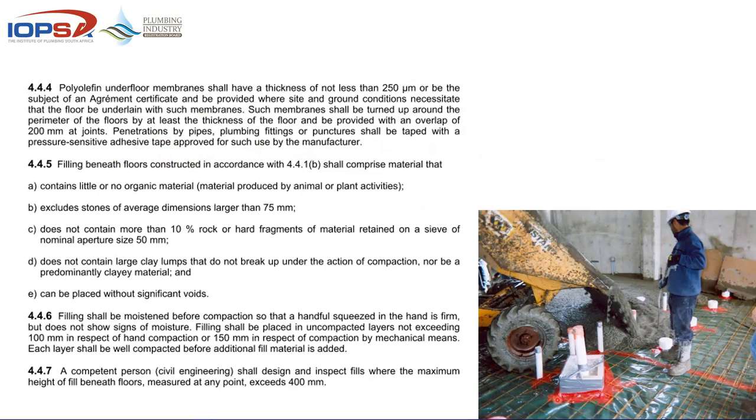In other words, if you have to have pipes in the floor, which is not always a perfect solution, then make sure that those things are taped off and cleaned off and sealed so that when the concrete is cast, we don't have moisture coming back into your building. I've seen jobs where floors have been chopped up because of moisture, and the plumber gets blamed, and by the time the job is actually opened up, you'll find that it had more to do with groundwater than actual plumbing or potable drinking water being the problem in that case.